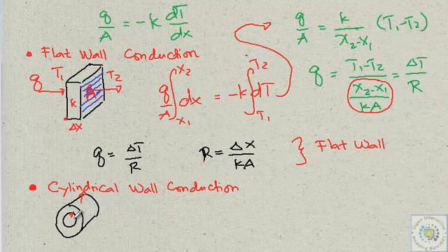But in this case, the area where the heat flows while the heat is still in the inner radius of this pipe is smaller, and that area is just given by this one. The area where heat flows is through the surface of this inner shell, like a tin can of radius r inner, and the heat flows to the surface of this.